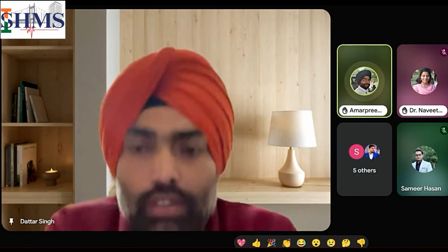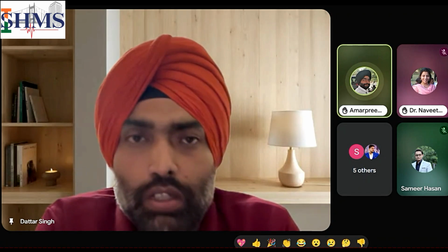And sir, one last question. Sure. Sir, we have basically done modal analysis with these sensors. So can we also create some stochastic model for vehicle bridge interaction? For example, in this case, there will be pedestrians or live load. Can we have some model based on these sensors only? For example, we have used this for modal analysis so that we can know the variation of pedestrians throughout the day or throughout the season. If we have the data, can we arrive at some model? Then we can perhaps use it for some other analysis as well.